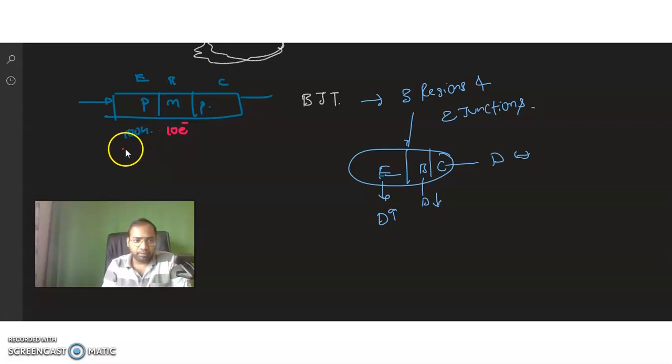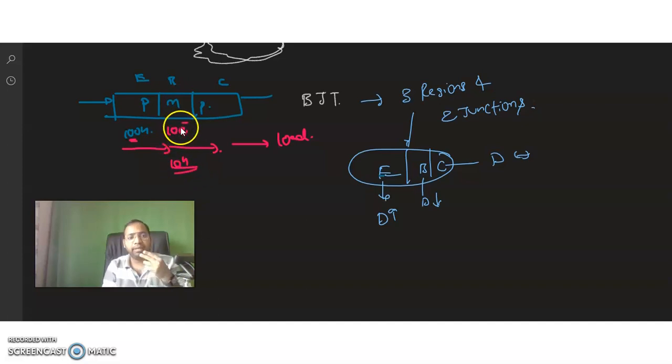Usually, the holes coming from the emitter will enter into the base and then enter into the collector, and from the collector it goes to the load. So in this journey, if the holes are crossing the base, then what will happen? Out of the 100 holes, 10 holes will recombine with the 10 electrons in the base. Out of the 100, if 10 holes are recombined, then how many holes will reach the collector? Only 90 holes will reach the collector.